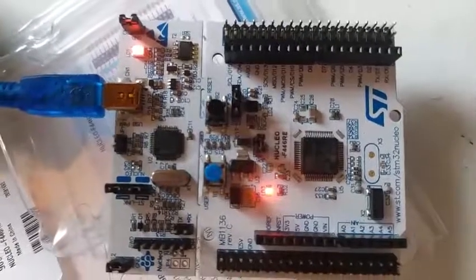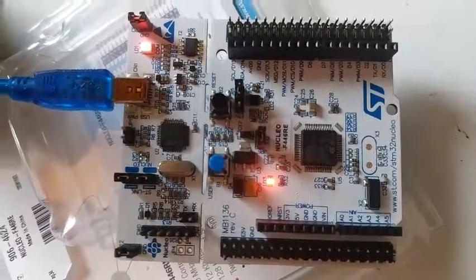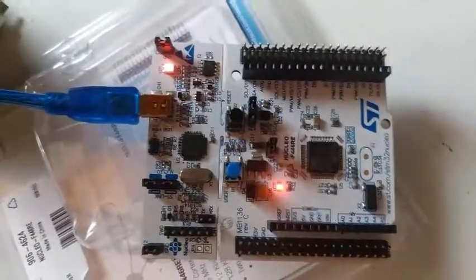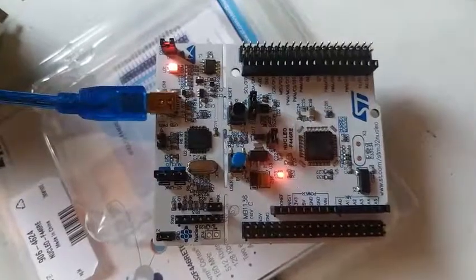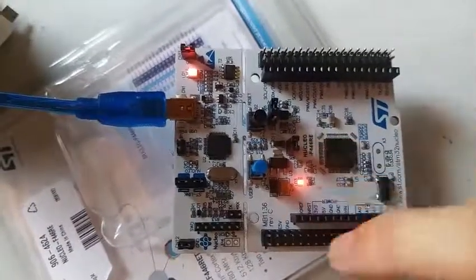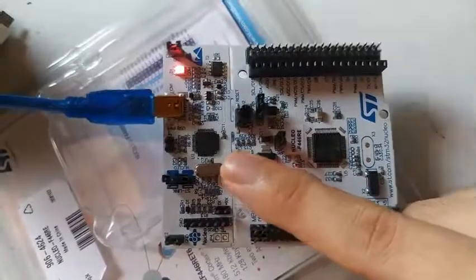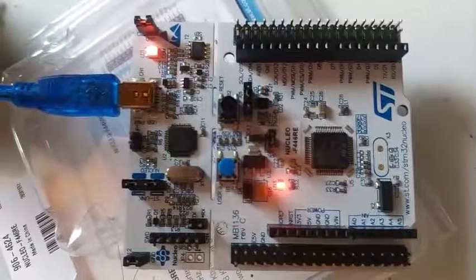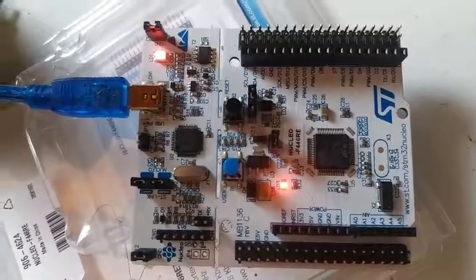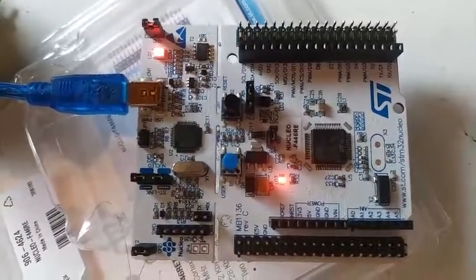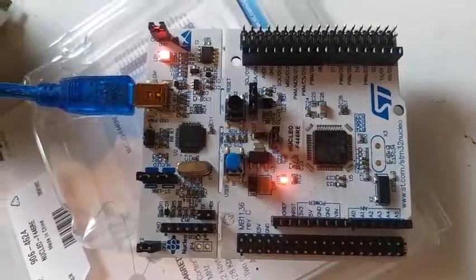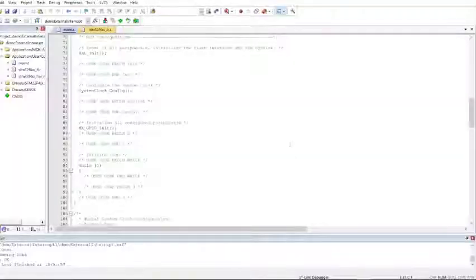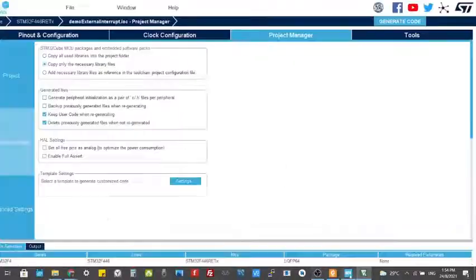Basically, it will interrupt the main while loop that you have in your main program, momentarily stop and execute the interrupt handler, and go back to the main program. The concept of external interrupt is quite important if you have a sensor that needs to be handled first before you continue the main firmware program. Now that we are done with the external interrupt, let's move on with the timer interrupt.